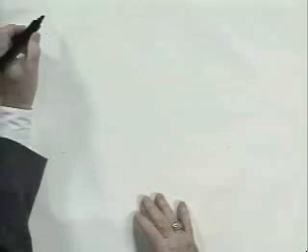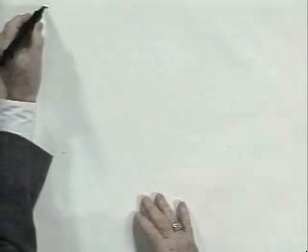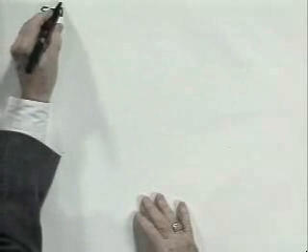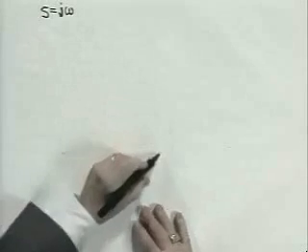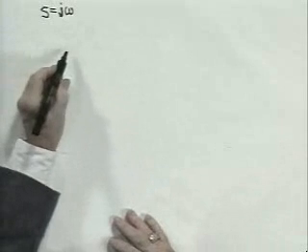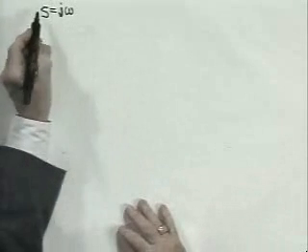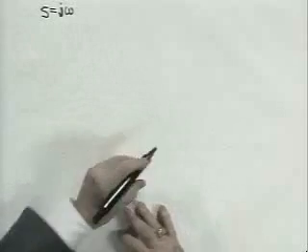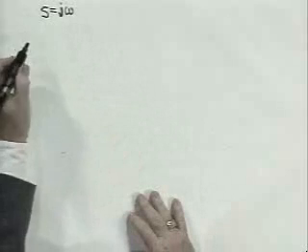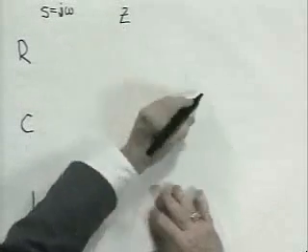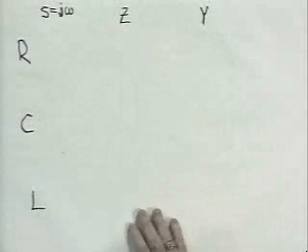And at this point, for convenience, although it has other implications, as we'll see somewhat later, I'm going to write j omega as S. This is a lowercase s. I'm not very good at printing lowercase s's, but just imagine that j omega, wherever it appears, is represented by the complex number S. And let me summarize for resistors, capacitors, and inductors the impedance and the admittance for these elements.